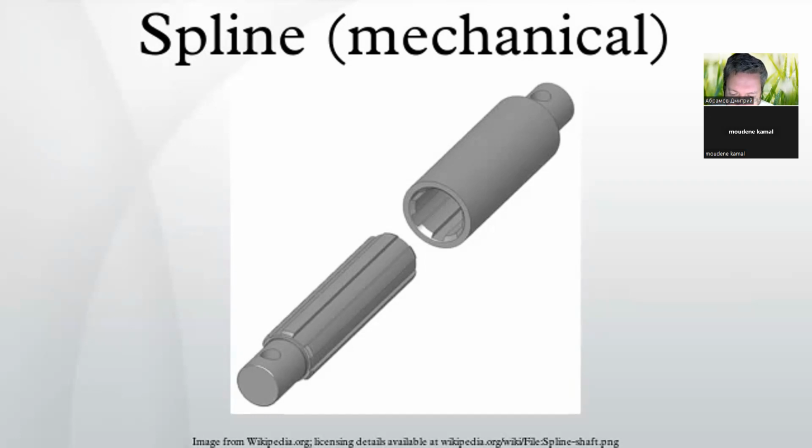Some cranksets feature modular spiders, where torque is transmitted through splines. Cassettes engage the freehub via a spline that is one groove wider than the others to enforce a fixed orientation. Disc brake mounting interfaces that are splined include Centerlock, by Shimano.